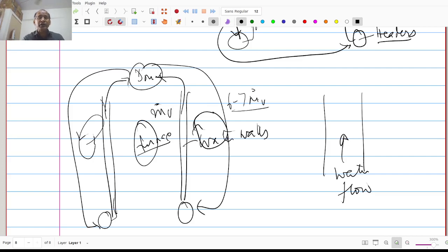So 1/6 or 1/7 of the water that flows through the pipes typically evaporates in the case of a power plant boiler. So this is a very ready example of forced convection boiling, forced or mixed convection boiling, where the water circulation is maintained by pumps. It's a forced convection boiling, and where there is a natural convection circulation, it's a mixed convection boiling.